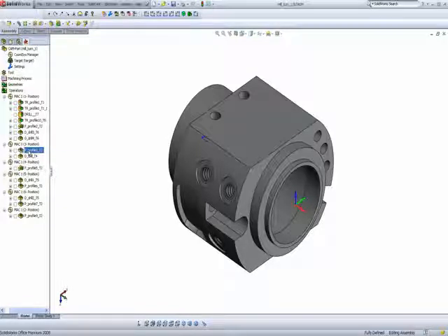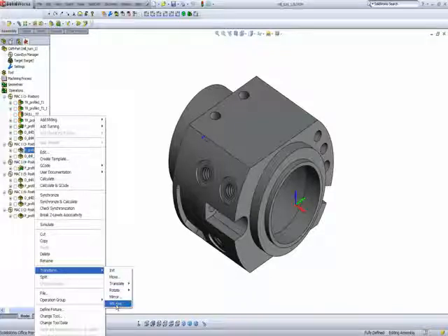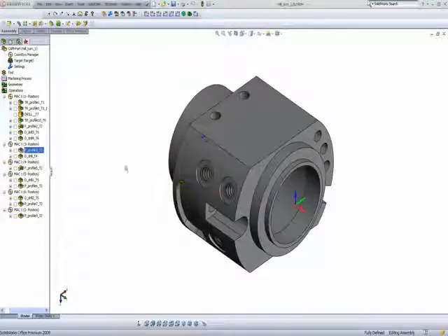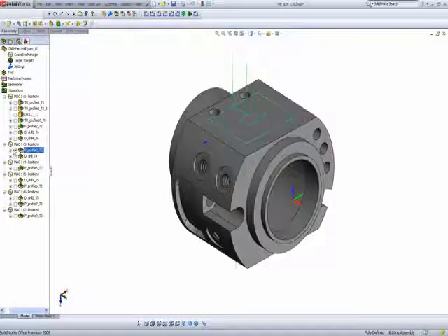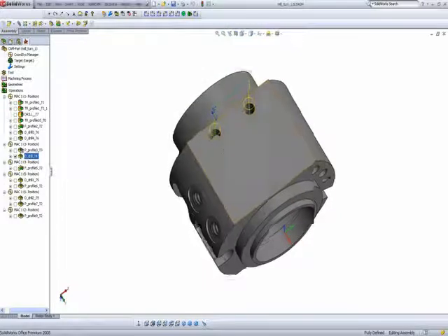indexial operation here. What I've actually done here is I've gone into what we call transform, and we have here 4 axes. And as you can see, what I've told it over here is to do my original operation and then add another operation turned at 180 degrees, thereby causing it to work on both sides, this side and on the other side. Now in my next operation, again, I'll be adding a simple drilling operation over here,